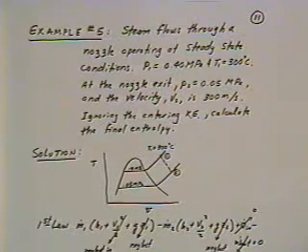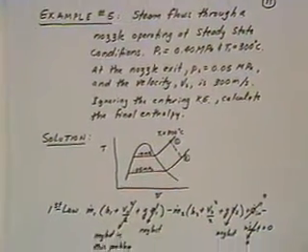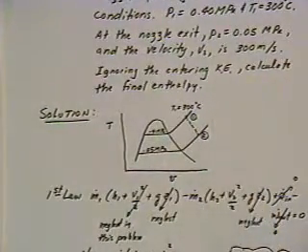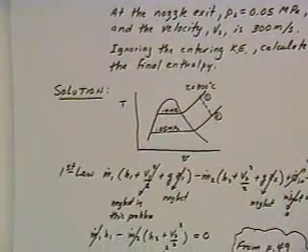The other usual assumption is that there is no work done, the heat transfer is 0, the change in potential energy is 0, and so we're left with an expression here where we're going to throw out all of the terms except the enthalpies and the exit kinetic energy. We're told to ignore the entering kinetic energy as well. Okay, so let's